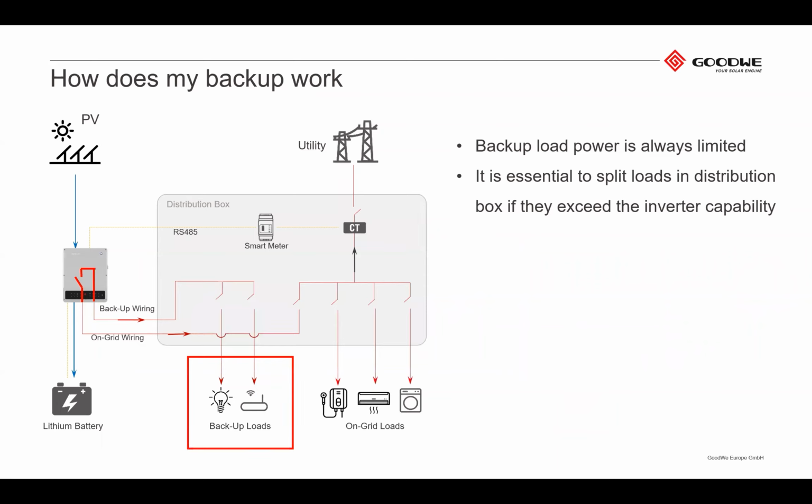Here's just a diagram of our systems. I'm sure all of you are quite familiar with this diagram. Internally in our inverter, we do have switching. What our inverter does when you are connected to the grid is essentially connect the grid and the backup together. That's why it's essentially seen as one load. So the inverter itself covers all load from the PV or batteries, especially if you're using general mode, which most customers use. It covers all the loads.